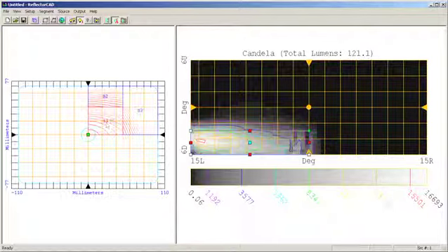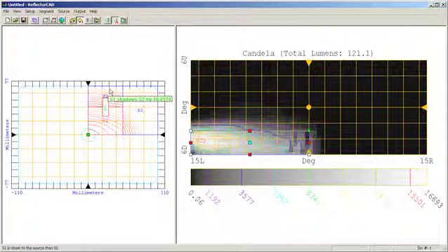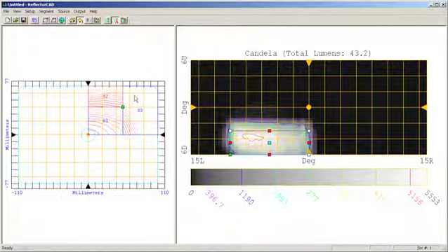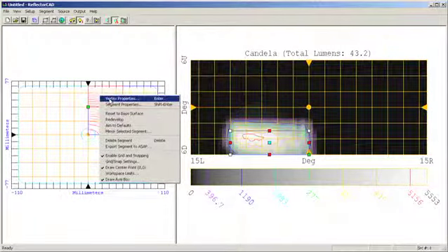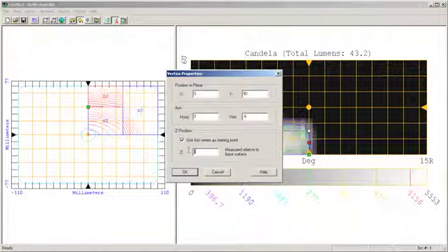By highlighting a segment, such as my center segment here, then with the Shift and mouse keys, I can determine how far in front of or behind a particular segment is with respect to another segment. Green is good, red is not so good. Now what I can do is come into each one of these individual segments, go to their vertex properties, and actually shift them with respect to one another.